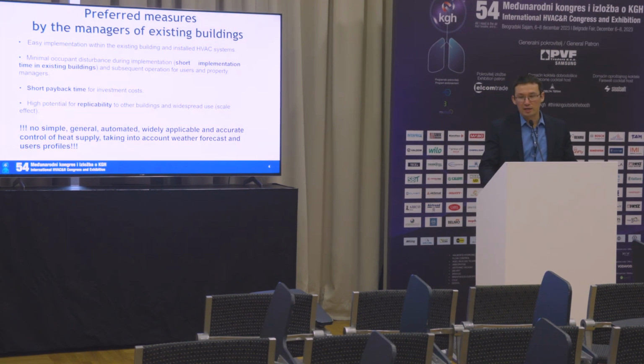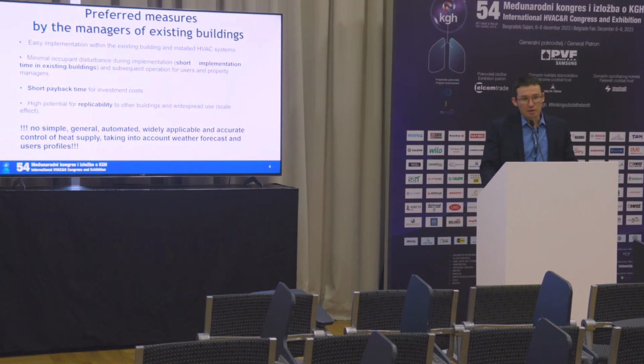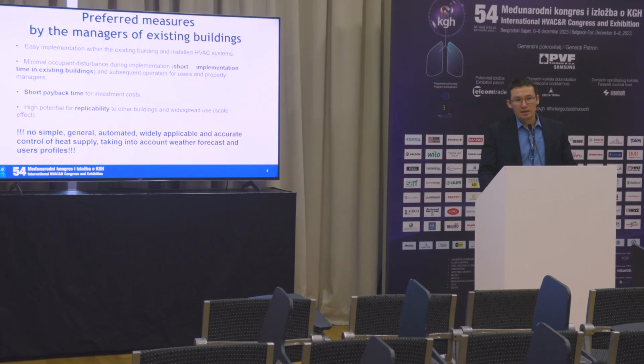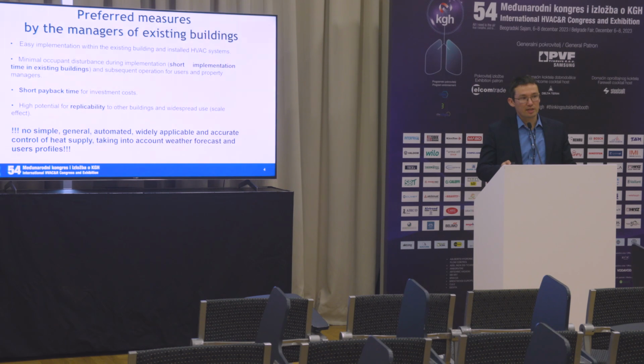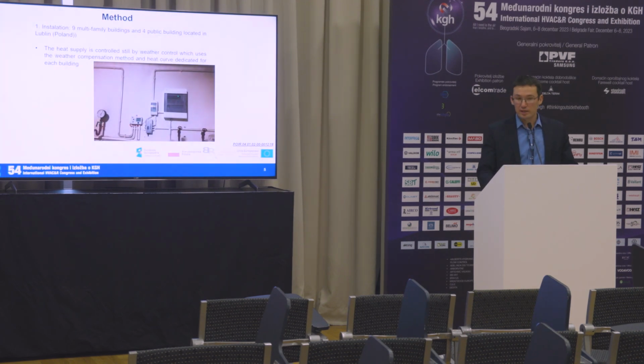But taking into account the thermal inertia of the building and of the heating system, we can react in advance and use forecast control, and in this way we can save energy. That's why we already developed a product. Now there is quite big interest in this in Poland. It is easy to implement and integrate with existing weather-based control.